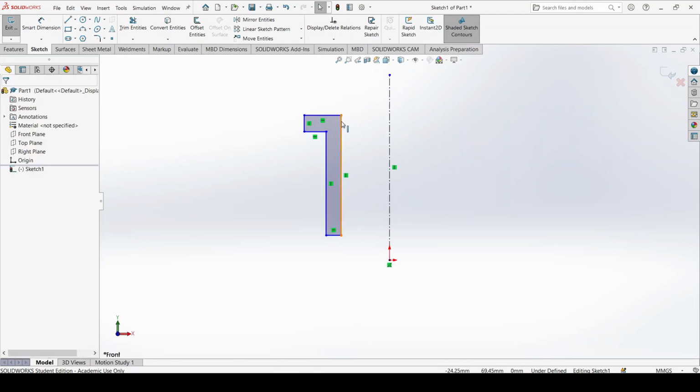It's quite important that I get them to close. And if I turn on shaded sketch contours, it will light up like this. Also, I'm displaying the relationships between the parts at this time. I assume you could do the same thing as well. I think it's easier when you're a rookie modeling parts in this way.